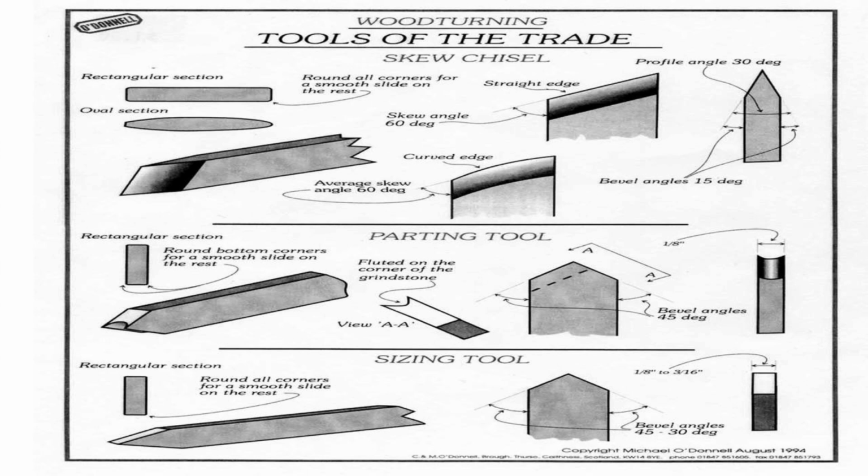And as Sam said, this oval skew is really good for planting potatoes. I don't care for it at all. You put it on a tool rest and it tends to rock. It's very hard to sharpen. So this, by far, is the profile I like the best on a skew. May I see it? I'm sorry? May I see it? Yeah, we'll pass them around.